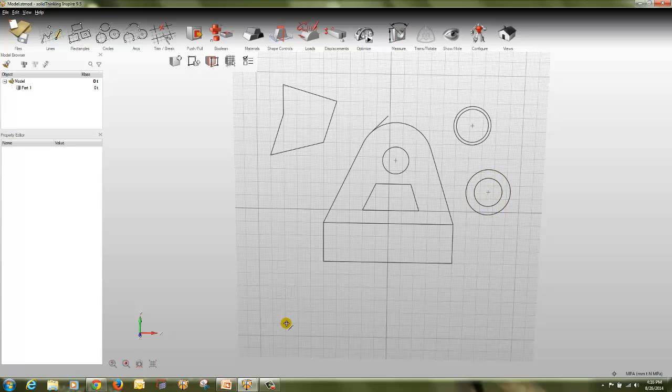So let's create one line, another line, right click, control left click, select both the lines, parallel constraints. So these will become parallel. Perpendicular constraints. So this will become perpendicular. So you can move this line. Like this. Control perpendicular. So now they will become perpendicular lines.